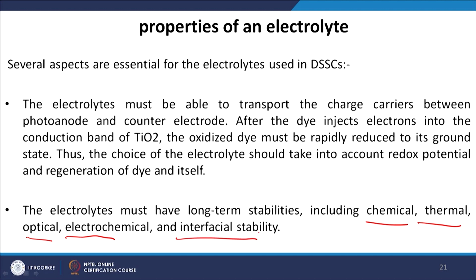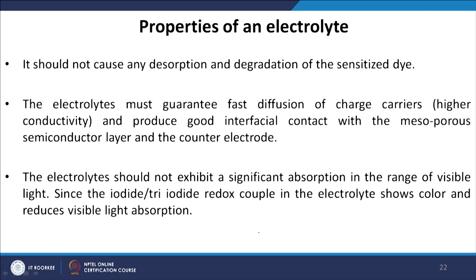Also the interfacial stability is very important, because in most of the cases in the solar cell device the interface plays a very important role. Now, these electrolytes are also there in the interface of the dye molecule and the counter electrode. So, that is why its interfacial stability is also very important while we construct the electrolyte solution. Finally, it should not cause any desorption and degradation of the sensitized dyes. Obviously, we have to be very careful that whatever dye we have chosen and whatever electrolyte we have chosen, they should not interact or chemically react with each other. Otherwise, a new complex will be formed and the whole thing will be changed.